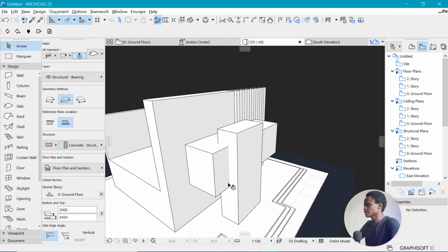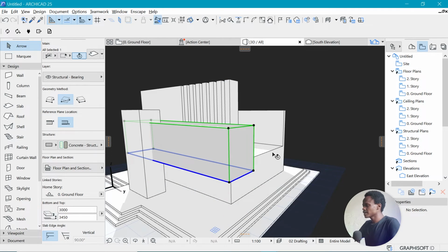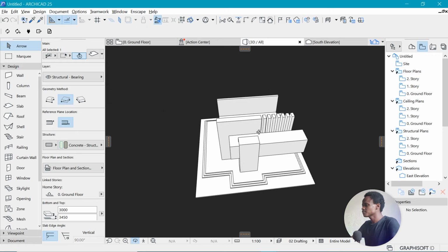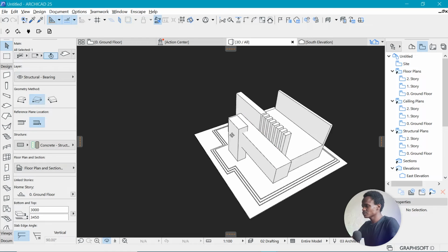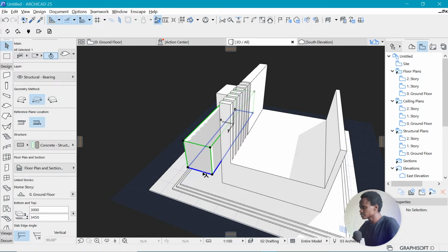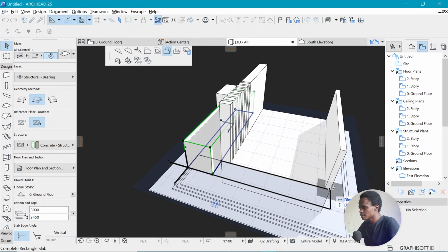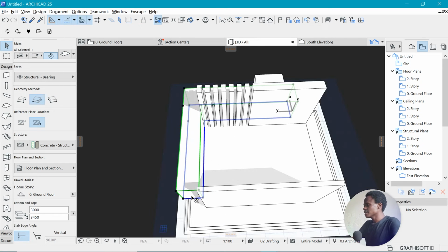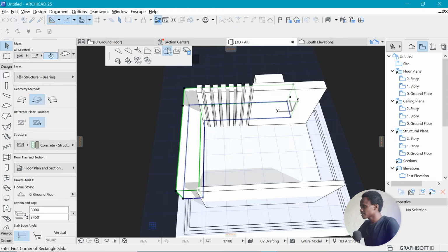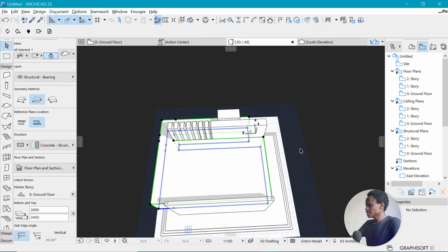So I think we may need to clean up a little bit here. And there we are. We take it all the way to the back, and it wraps around and continues all the way to this other side. So let's continue that form. How do we do that? By clicking on the edge, and we get this palette where we can add to the form by clicking, and then let's add it right there. You can see that now we have added that form, and as well we can add one more form by making sure that we are adding to polygon, and there we are.